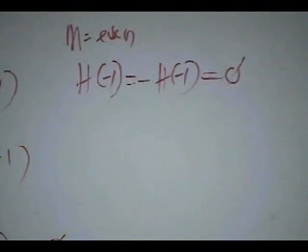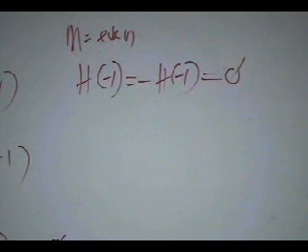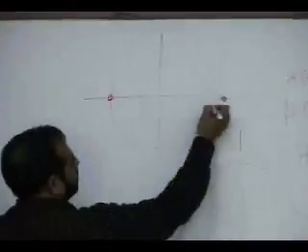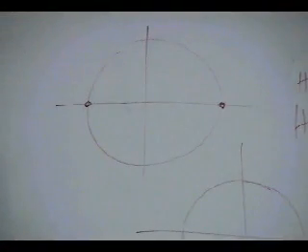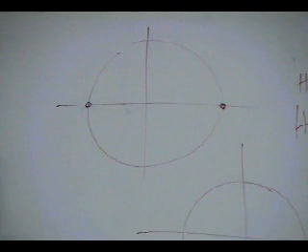So what does it mean? If m is even, it means it is type 3, so there will also be a 0 at minus 1. Where is minus 1? At pi. So for type 3 you can have neither a low pass filter nor a high pass filter, no matter what you do.